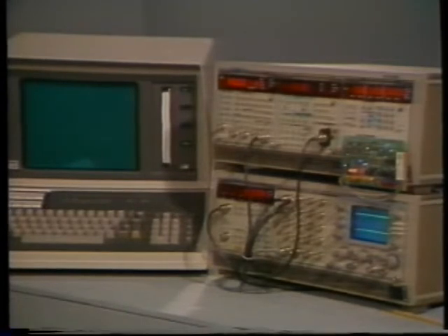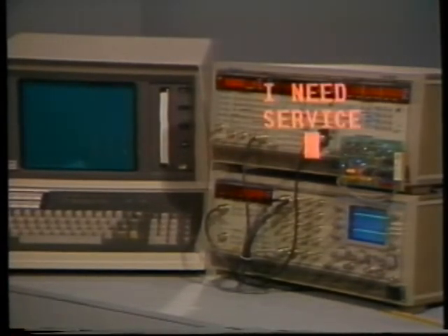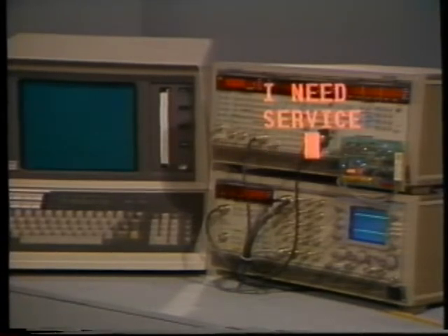One of the most important concepts in IEEE 488 is the service request, SRQ, and the polling methods used to handle the requests. The service request is the GPIB-defined method for a device to request service from the controller. This technique is often referred to as an interrupt. The SRQ line, which is one of the 5 lines of the management section of the bus, functions as a wired OR. If any device on the bus asserts SRQ, that sets the line true, and the controller knows that some device needs service. It doesn't know which device until it conducts a poll.